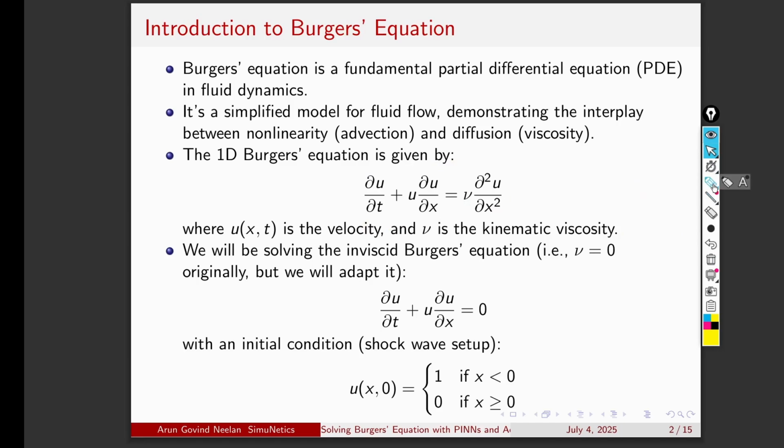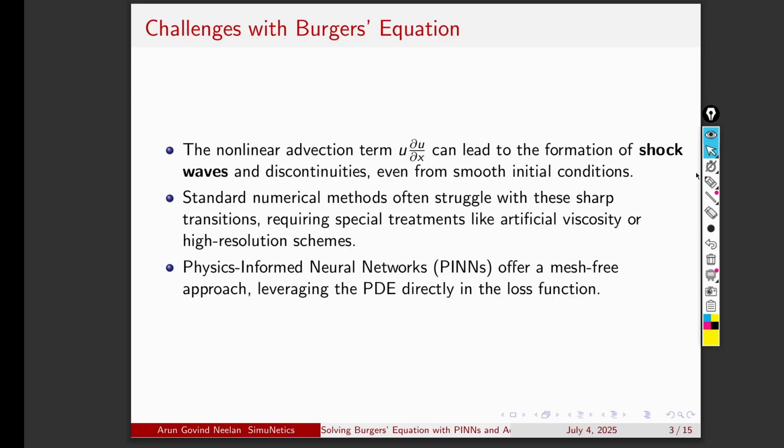In this case, we have considered a shock-like, step-like initial condition, so that we will get a shock. Over time, the Euler equation will anyway produce a shock, because the characteristics intersect, but it will take some time. But if the solution itself has shocks in the profile, the characteristics immediately intersect. If we have a shock like this, we will be calculating derivatives across the shock, which is not good. So we will use viscosity to smoothen this profile.